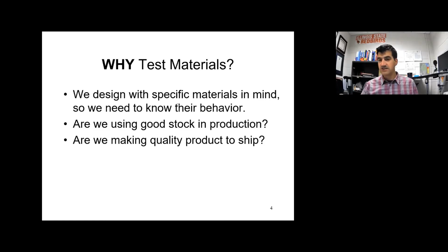And you need to do that in order to design the part, because otherwise you don't know whether to make that pitch stud 1 inch in diameter or 1.5 inches in diameter. That's all based on the strength calculations based on the known properties of the materials. You also want to verify that you're using good quality stock in your production and making sure that the products that you're making are going to meet the specifications for your customers.